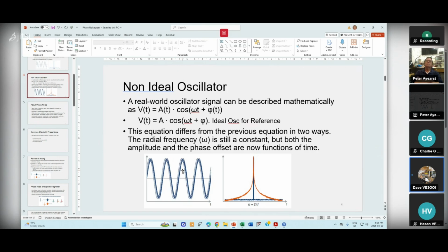The other thing it could be is quantization error, because if it's an ADC converting the signal into a digital signal, all ADCs have a quantization error, and they'll say plus or minus 1 bit or half a bit.